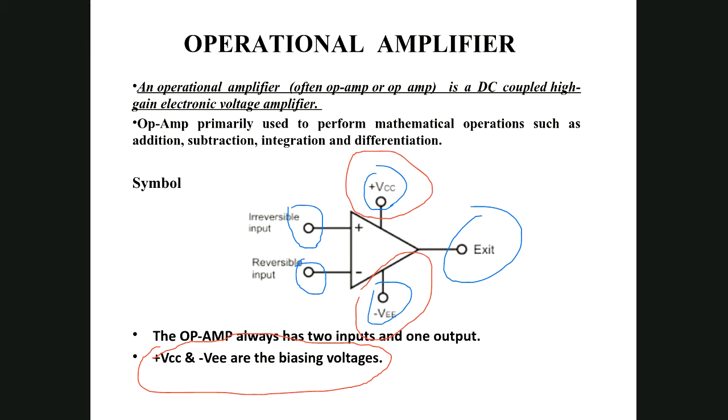You mean by balancing, the turn on and off? Yeah. You remember a transistor can be used in three regions: cutoff, active, and saturation. When both junctions are forward biased, it is called saturation or on. When both junctions are reverse biased, it is called cutoff or off, right? So how can you achieve this by applying these two voltages?